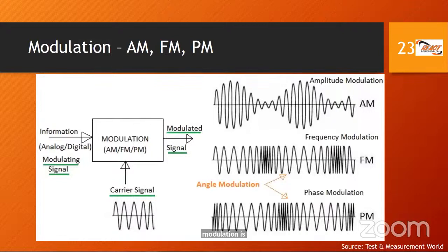All right, so we need to know about a couple different types of modulation. We did say that modulation, we're talking about voice, but it could also be digital modulation. As we'll see in a little while, we do connect computers to amateur radio equipment, and they let the computer do the talking, right? But typically we will be speaking voice, speech, a mode that's called phone. We'll speak and the radio will generate the carrier wave or the RF wave and impose our voice on it. But there are different ways that that voice could be imposed on the carrier signal. And those are called the various types of modulation.